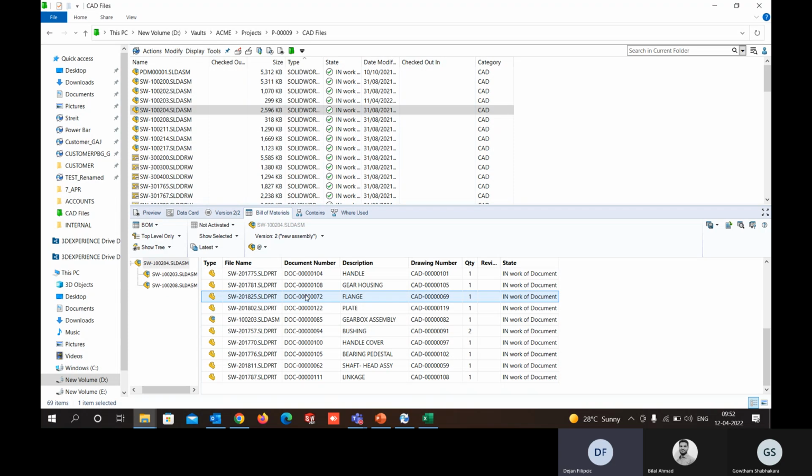So let me try to rephrase it. What you're saying is that the BOM that comes from the assembly is locked to the assembly. The definition comes from the assembly. When you save it, you can add entities to that BOM. They're not necessarily related to the 3D, they're not being driven by the 3D. And because you saved it, you can have multiple versions that are saved. And once you have those saved versions, you can run a comparison between them. Is that what you're saying?